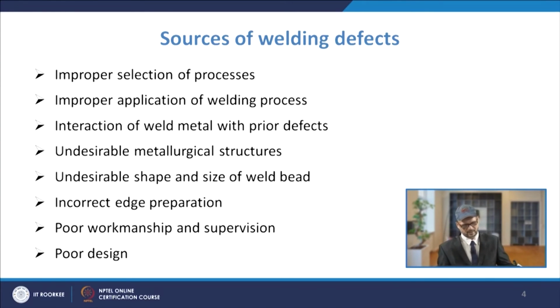So that will lead to many kinds of defects, like there may be lack of fusion because of improper fit-up or improper edge preparation. Then you have cracking, or many types of defects that originate from incorrect edge preparation. Then you have poor supervision, poor workmanship.